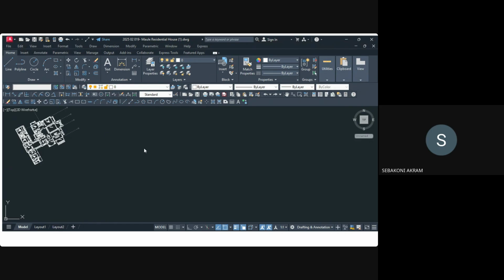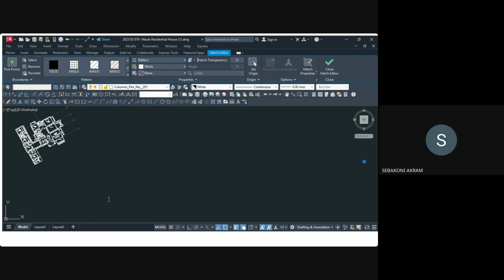So you see, you still have other layers, meaning that there are some drawings that are not being deleted. So you come here, you could do Control A, or you select all, right click, you come to quick select. Quick select, you come to select by layer. You getting me? So you come and see which layer is having column pins. You say okay. So you see this. Are you seeing that? So we didn't delete that.